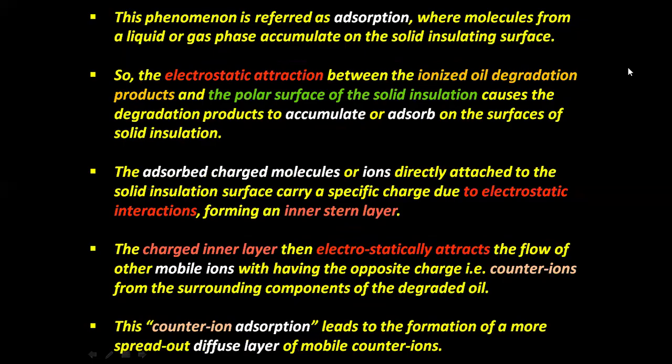So, the electrostatic attraction between the ionized oil degradation products and the polar surface of the solid insulation causes the degradation products to adsorb on the surfaces of solid insulation.